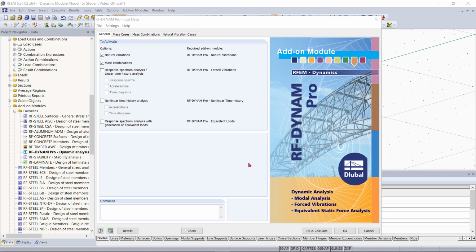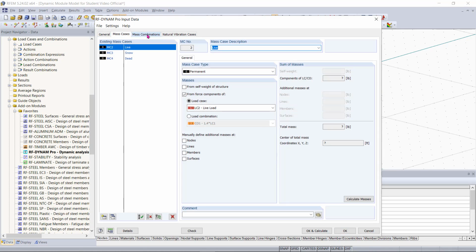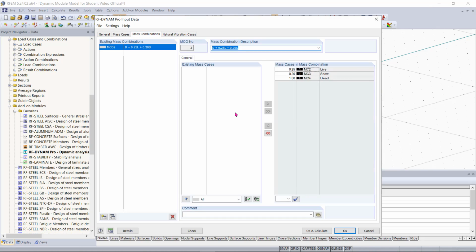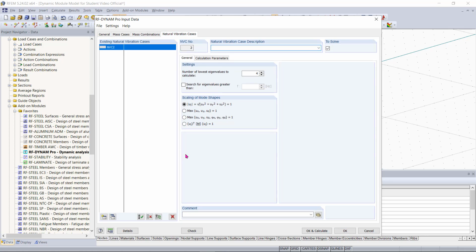If you missed part 1, I do recommend going back and watching that, because in part 1 I discuss how to enter the input data that's needed to run a natural vibrations case on a structure. Right now I have all of my input data entered in the module, such as my mass cases along with my mass combinations. I also have everything set under my natural vibrations case tab. So all I need to do now is hit OK and calculate to run my calculation and see my results.